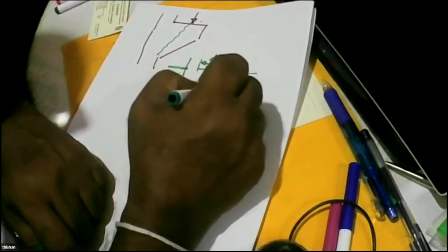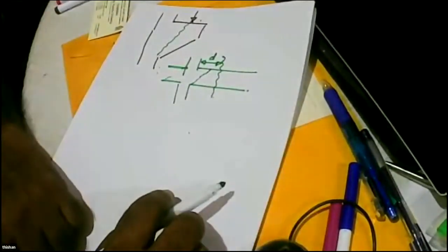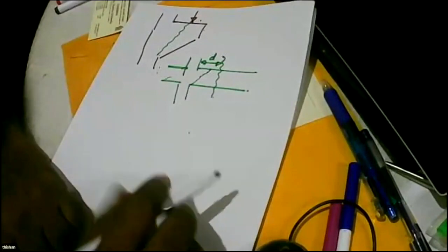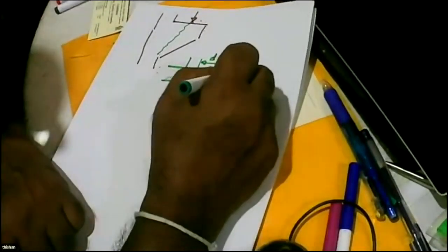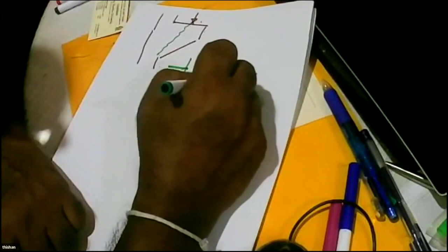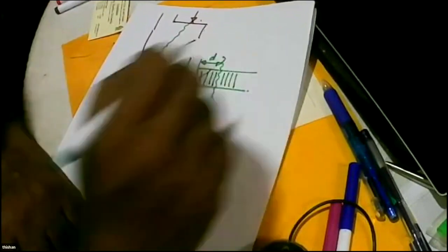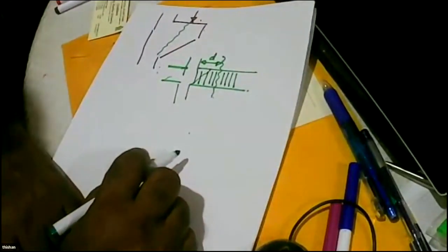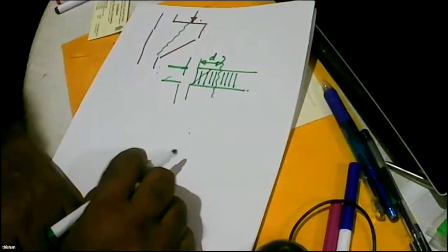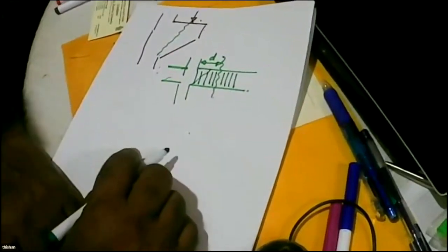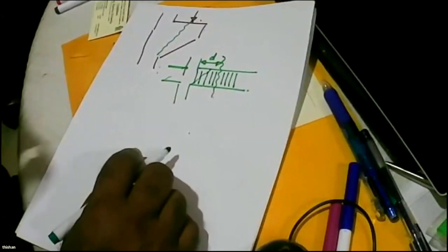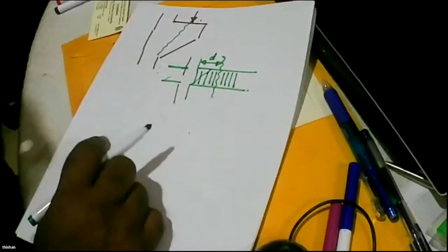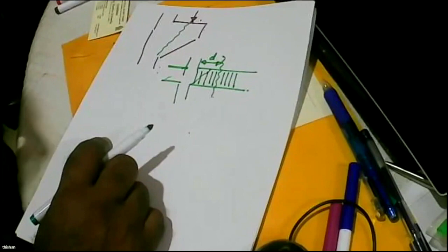Check the shear D away from the face of the support. Whatever the links that you get here, provide the same links up to the support. Is that clear, Bandhuka? Yes, sir. Because of enhancement, we are taking D away. Only because of this enhancement, because at the very close to the support, you can't get shear failures. Got it? Yes, got it.